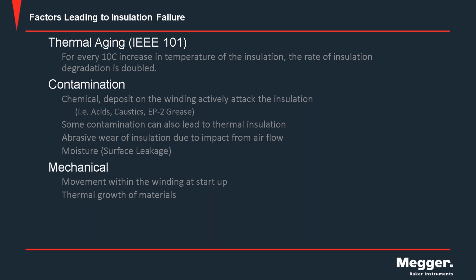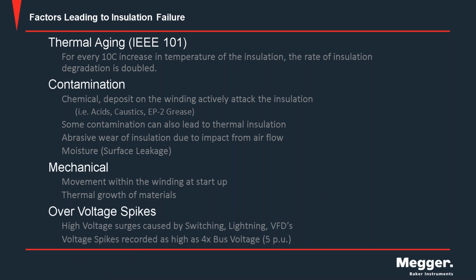That high inrush current, of course, is going to yield as a squared function of current, I squared R, a high thermal impact on that winding, and it'll grow thermally in the slots. The winding will elongate in the slots, and that elongation or growth of the material of the coil, or the movement of the coil during the high torque feedback on the coil, will cause that insulation to wear out over time. So there is a mechanical element there as well.